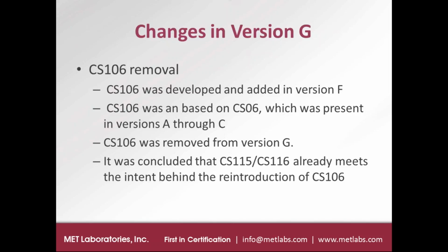And the committee for MIL Standard 461 concluded that the other test methods, CS115 and 116, already meet the intent behind the reintroduction of CS106. CS106 had a kind of double exponential pulse. So it was another transient conducted susceptibility test.